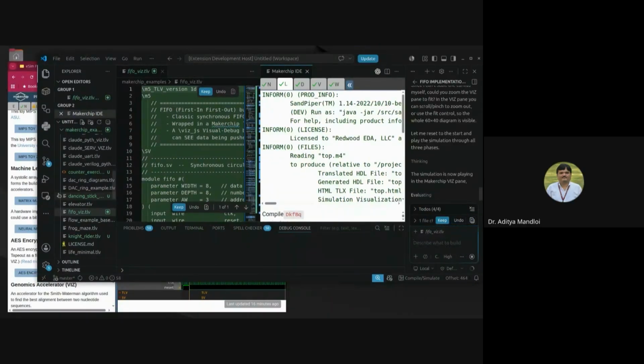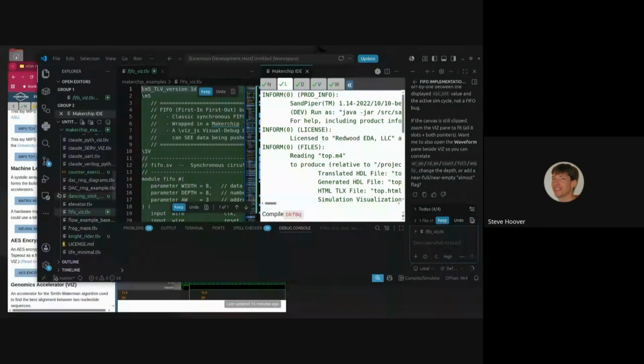Just like use clock gating or power gating scaling concepts, if we want to involve in our Verilog code, how do we start the automation algorithm in Verilog? How do we write it? Right. Logic synthesis is not in Makerchip itself, but you can certainly run Makerchip on a platform that has, say, Synopsys tools installed so that you can do logic synthesis, and just do that outside of Makerchip, right?